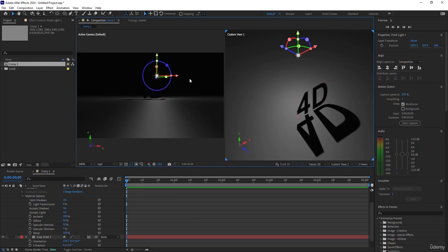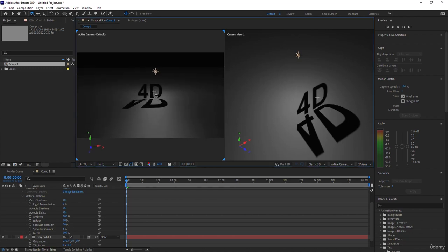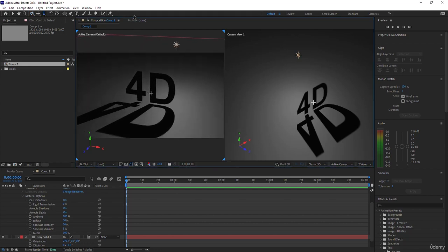Okay, right now none of them is visible from our active camera, so we need to zoom in and we need to move our camera. To do that, there are 3 camera controls. So let's select the first one. This is the orbit. Let's drag it a little bit. Drag your mouse slowly so that you can see. Okay, so I like this view. Now we need to zoom in. So in order to zoom in, I'm going to click this one. Let's zoom in a little bit.